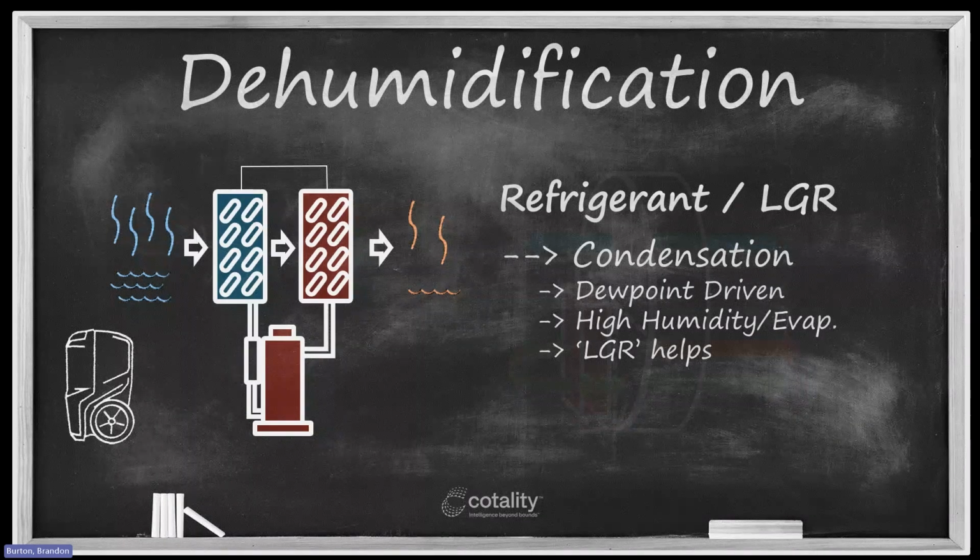What a refrigerant dehumidifier does is it takes the sponge out of that bucket and puts it over a drain or a sink and squeezes the sponge, right? When I squeeze that sponge and lower the capacity of the sponge, water falls out. And that's what's happening on that first coil. The air is being cooled, which reduces the energy to support moisture. It lowers the capacity, if you will, in simple terms. That wrings moisture out of the sponge.